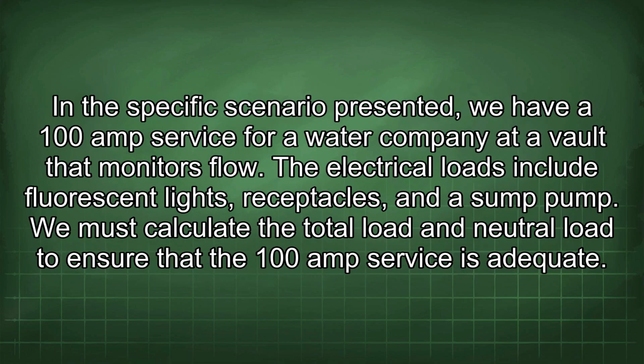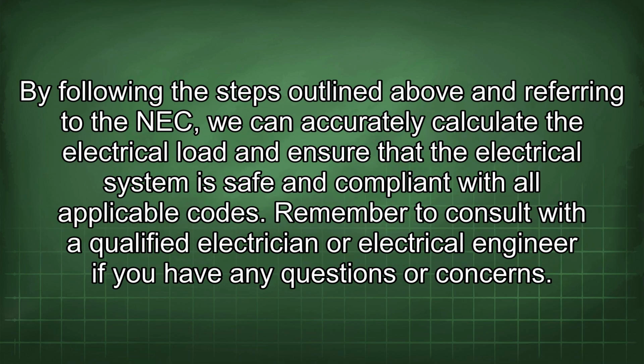In the specific scenario presented, we have a 100 amp service for a water company at a vault that monitors flow. The electrical loads include fluorescent lights, receptacles, and a sump pump. We must calculate the total load and neutral load to ensure that the 100 amp service is adequate. By following the steps outlined above and referring to the NEC, we can accurately calculate the electrical load and ensure that the electrical system is safe and compliant with all applicable codes. Remember to consult with a qualified electrician or electrical engineer if you have any questions or concerns.